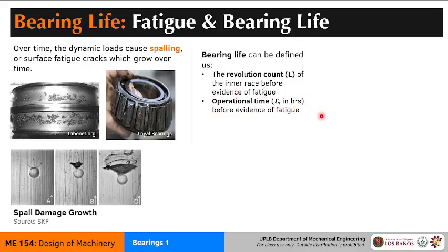Even though this is the last item, please keep in mind the difference between the variables used. When you see a very fancy curvy L, it usually denotes operational time, which is normally in hours. It can be given in minutes, but you have to convert them into hours. There's a reason why later. So, again, there are two possible quantities. You can just count the number of cycles, or you can count the number of hours that the bearing has been active.